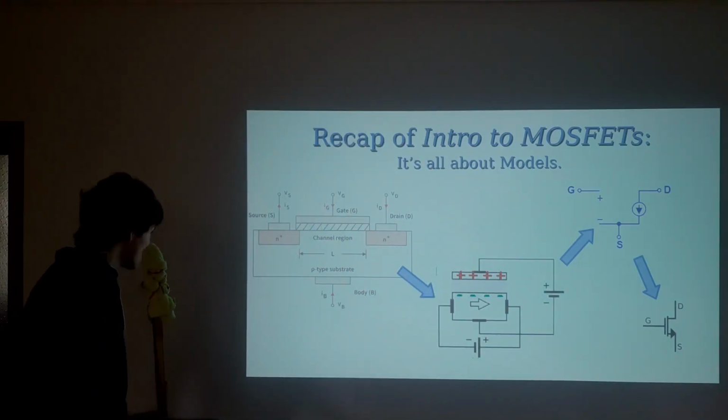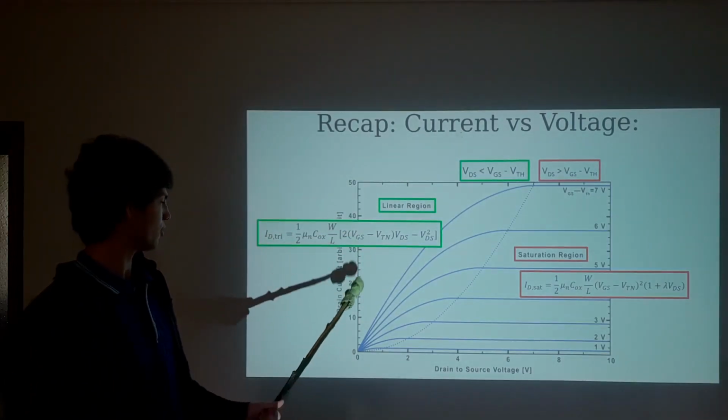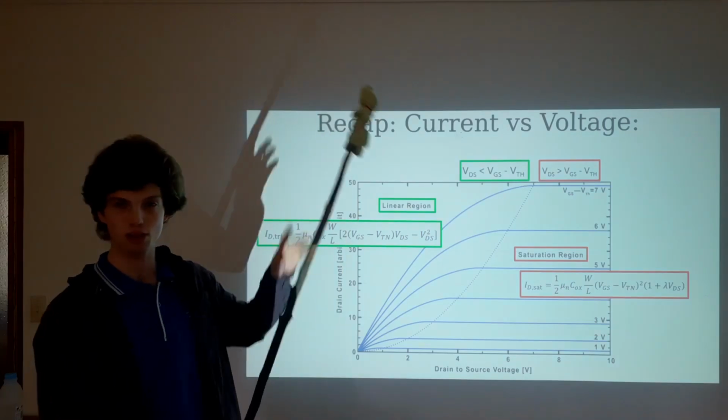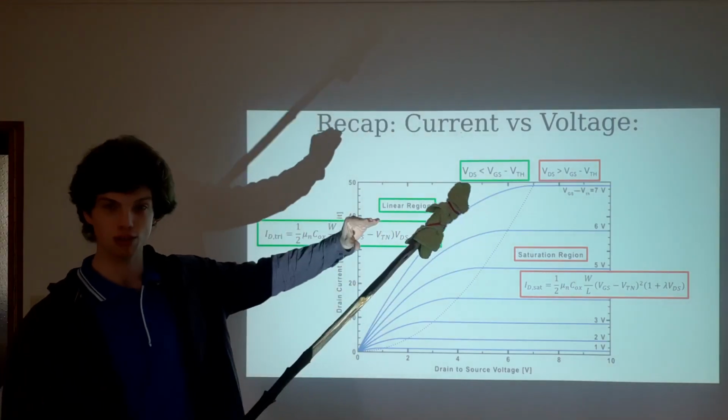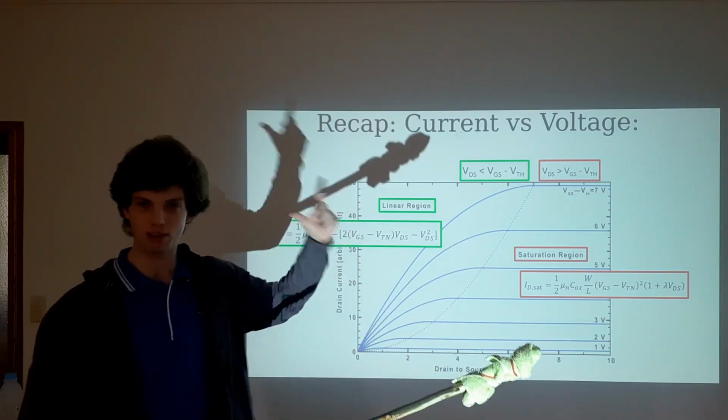Right. So the other really key thing we saw yesterday was the behaviour of this. This is the drain current, so there's only one current in these MOSFETs. It goes from the drain to the source. Remember, the gate draws no current, and that's what makes them great. Makes them extremely efficient. I waved around a CPU.